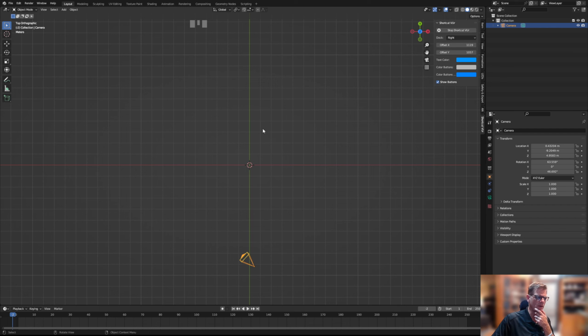And the first thing I want to cover is how to enable the Skybrush add-on. So you're going to download the zip file. Do not unpack it. Just download the zip file. And you're going to go to Edit, Preferences. Of course, you'll remember where you downloaded it, probably your Downloads folder. Wherever it is on your computer, go ahead and select the zip file and then just install add-on. And that's all you have to do. There's nothing more that you need to do for that.